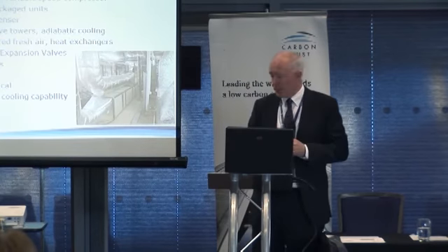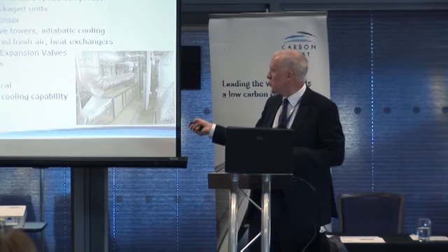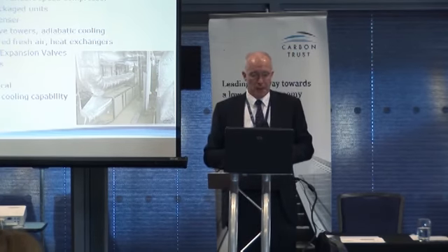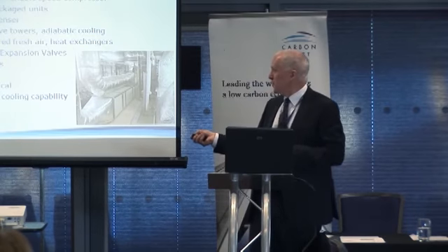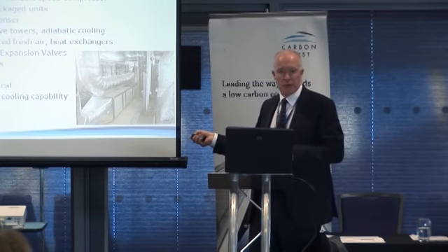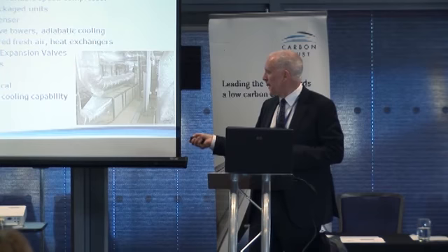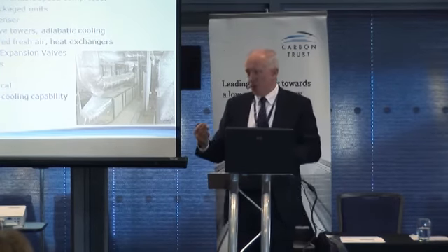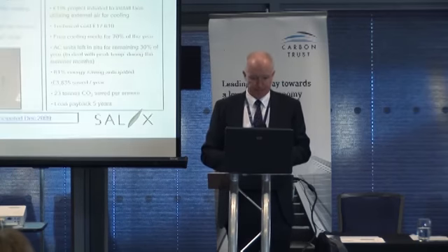There are also liquid pressure amplification, all sorts of technologies to improve the efficiency of your plant if it's there. Typical COPs on refrigeration are about 2.5 to 3, but with some free cooling, people are coming out with COPs now for data centers of about 6 to 10. Huge improvement in efficiency can be achieved.